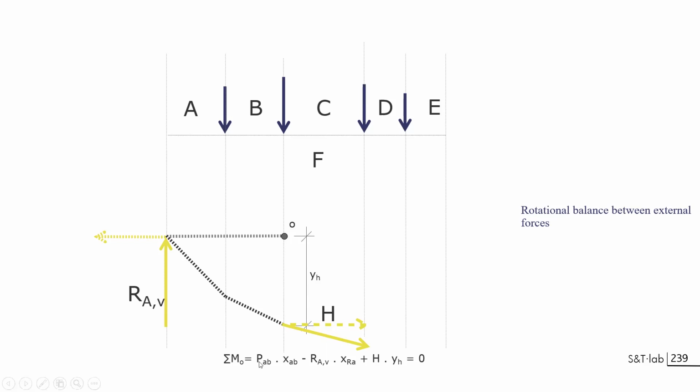And so it shows you an equation in which we have this force with this lever arm and this force with this lever arm that will be equated with the horizontal component of the funicular line. So it will show you that this is exactly the same equation you have when you were demonstrating the bending forces. So to have the value of these bending forces, you just need to know the horizontal component of the force along this funicular once it has been drawn, and to multiply by a distance you have here.